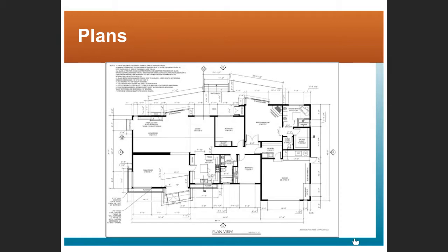Right, so a plan drawing, let me see where this sits in the textbook. If you happen to be following along, a plan drawing means that we are, again, looking down from above. We're typically slicing the building through at the 4-foot level, give or take, and we're showing the features that exist in the building.